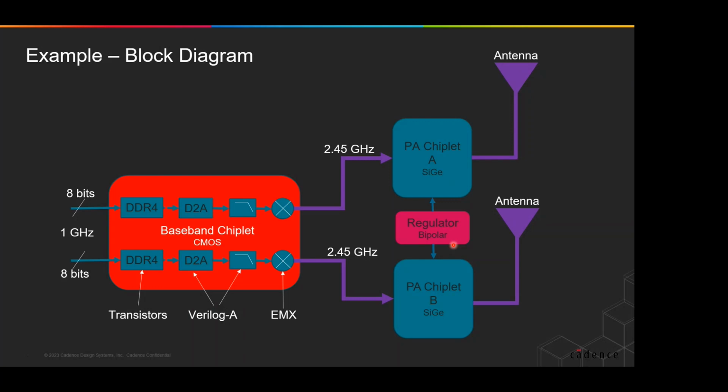We included transistors in the baseband chiplet. We included some Verilog A in the chiplet. We extracted part of the chiplet using EMX. We extracted the interconnect using Clarity. We have SiGe, CMOS, and bipolar technologies, all on a single organic laminate design.